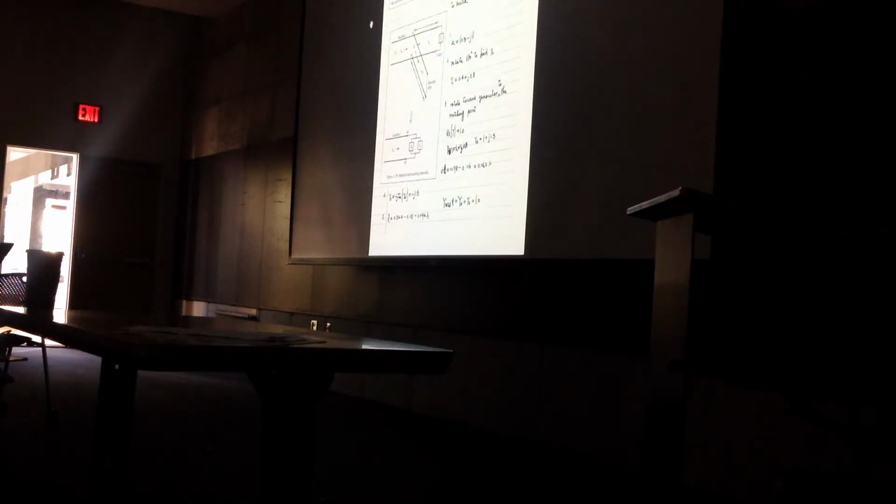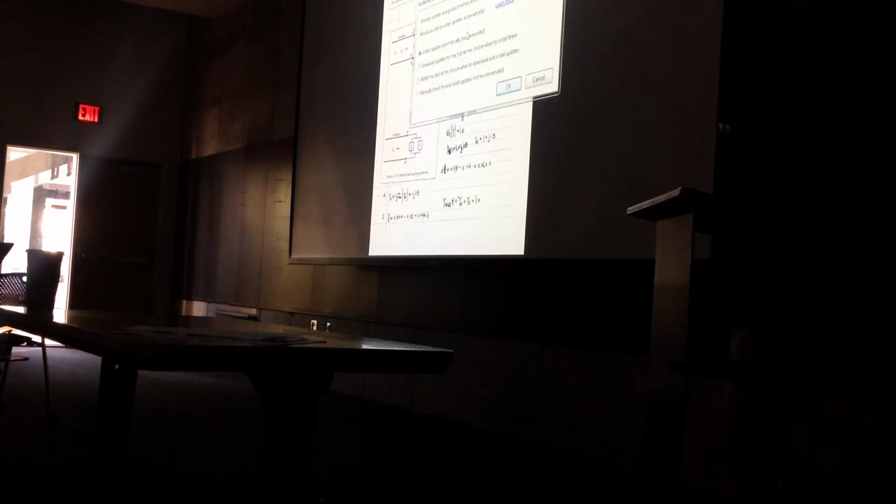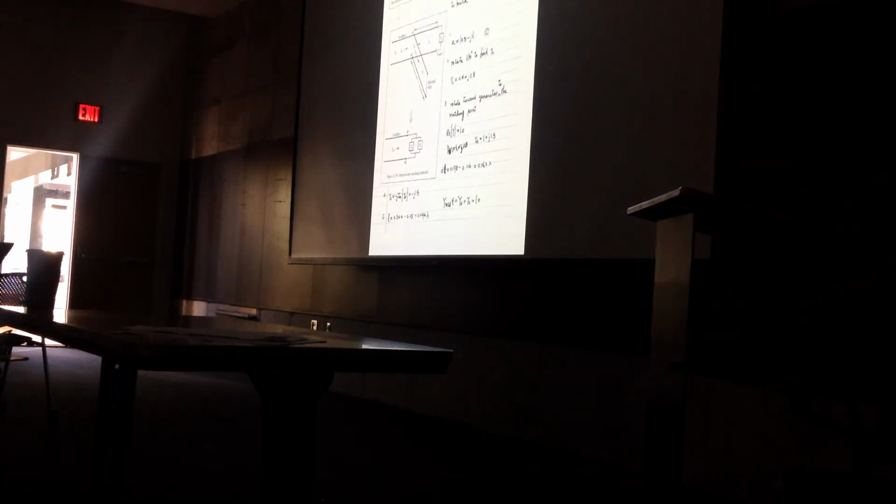So let's look at this example. We have the load, which is 25 minus j50, and your transmission line is 50 ohm. So this is the first step. Step number one, from that load impedance, I compute the normalized impedance, which is simple, just taking that and dividing it by 50. Once we do that, we find our normalized impedance to be 0.5 minus j1.